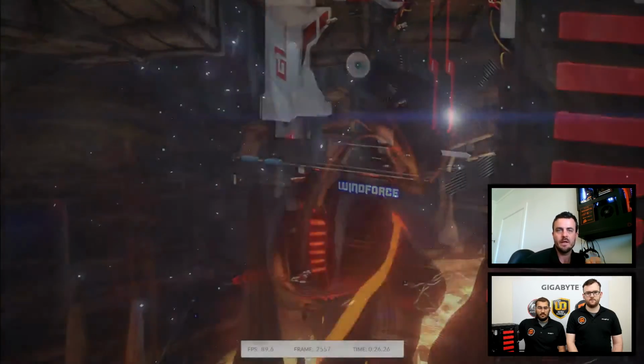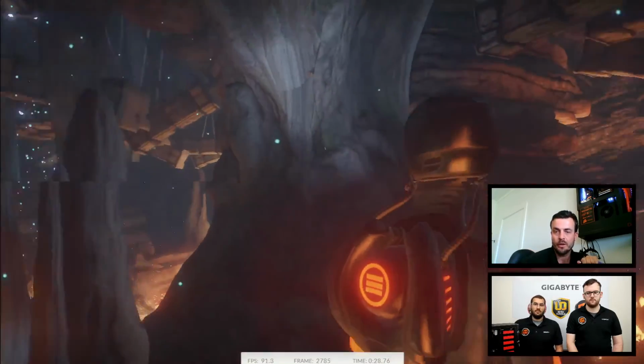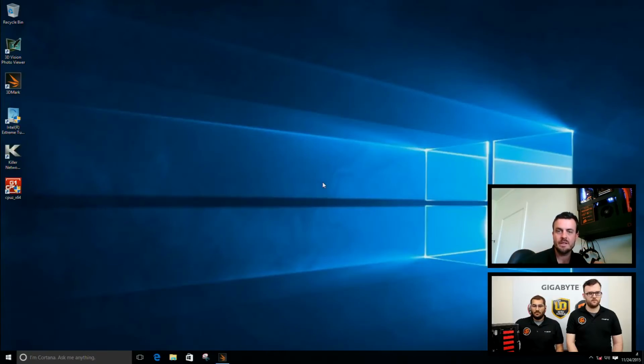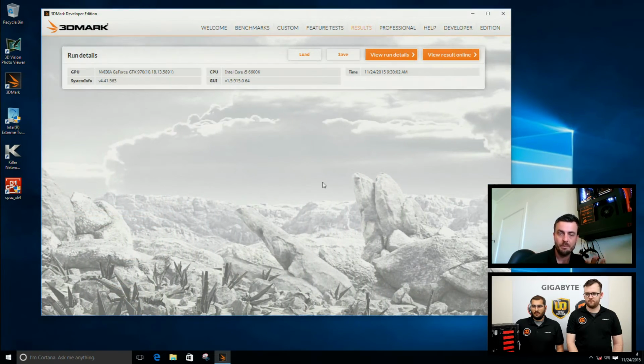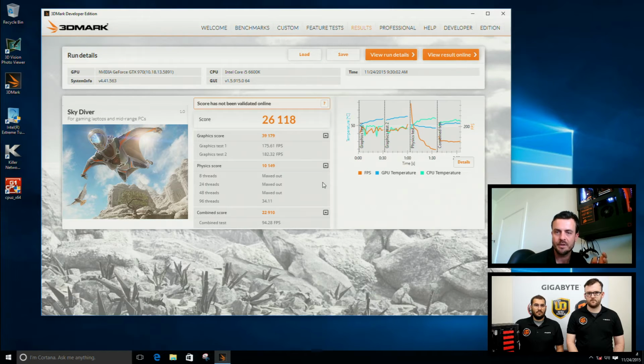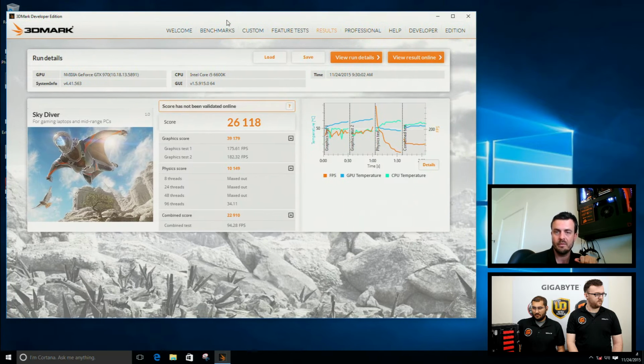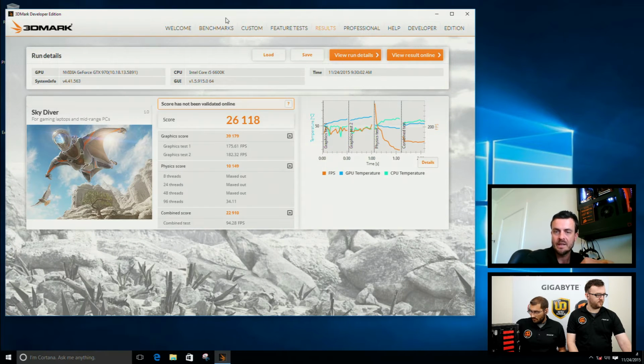So what some people do is they will overclock a system to say 4 gigahertz, and then look to reduce the CPU voltage as much as possible to try and keep the CPU temperature down, and also power consumption down. So for example, we are running at 1.35 voltage. You could probably get away with 1.1 voltage or 1.05 V. So 20 or 30% reduction in power consumption by decreasing the voltage in CPU. So it really depends. Some people like to go max, some people like to actually reduce power consumption and heat.